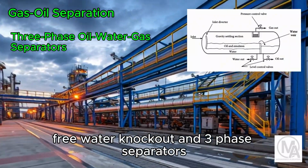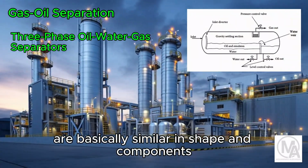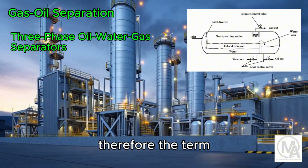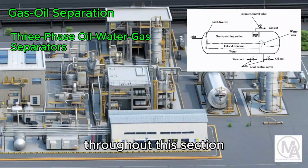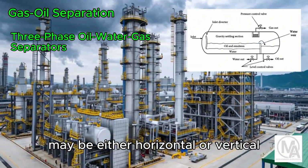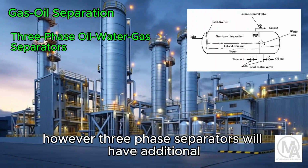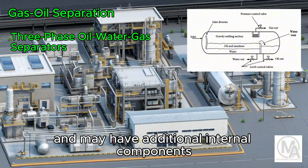Free water knockout and three-phase separators are basically similar in shape and components. Further, the same design concepts and procedures are used for both types of vessel. Therefore, the term three-phase separator will be used for both types of vessel throughout this section. Three-phase separators may be either horizontal or vertical pressure vessels, similar to the two-phase separators described above. However, three-phase separators will have additional control devices and may have additional internal components.